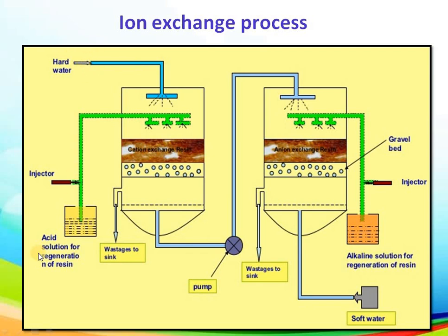Acid is passed through the cation exchanger bed, and similarly the alkaline solution is passed through the anion exchanger resins. This process is known as regeneration.